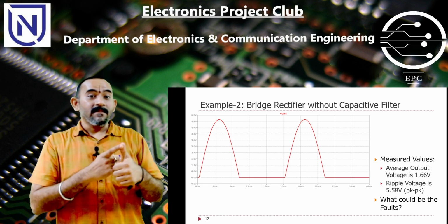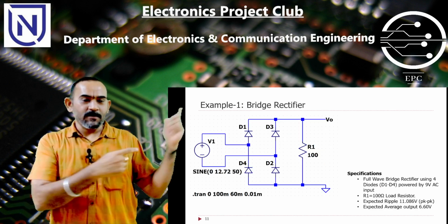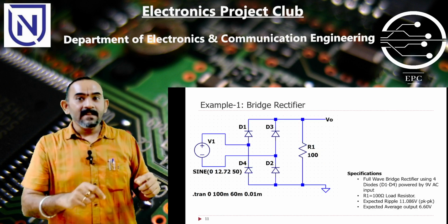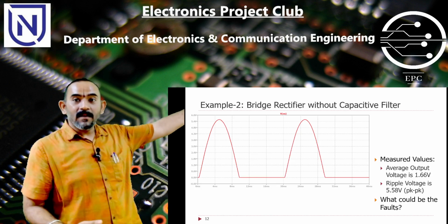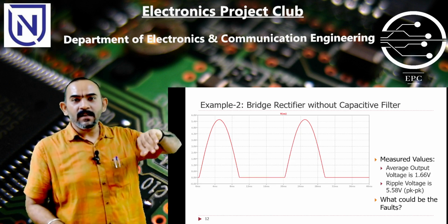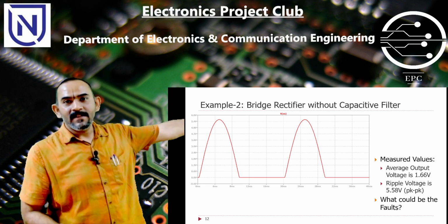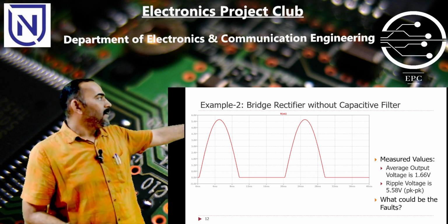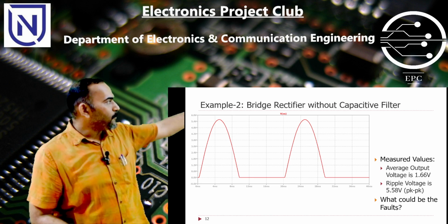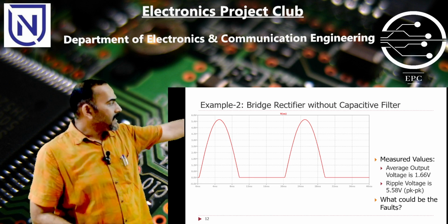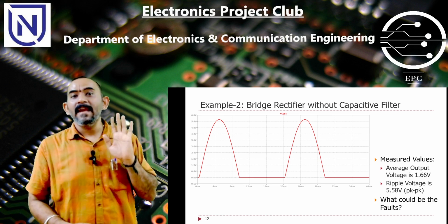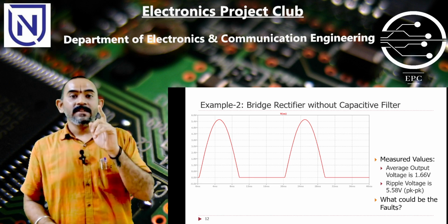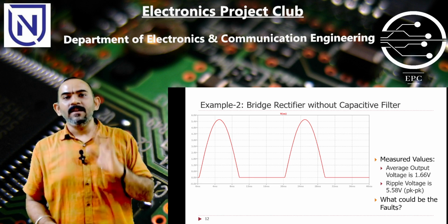Now, we may not apply these steps we discussed as is, but by default we do that. If you didn't know how a full wave rectifier is supposed to work, you would not be in a position to detect this, right? Since we know we are supposed to get 2 pulses, but here we are not getting the 2 pulses, I know there is a fault. It is behaving like a half wave rectifier. So diodes are not working. Which diode is not working?